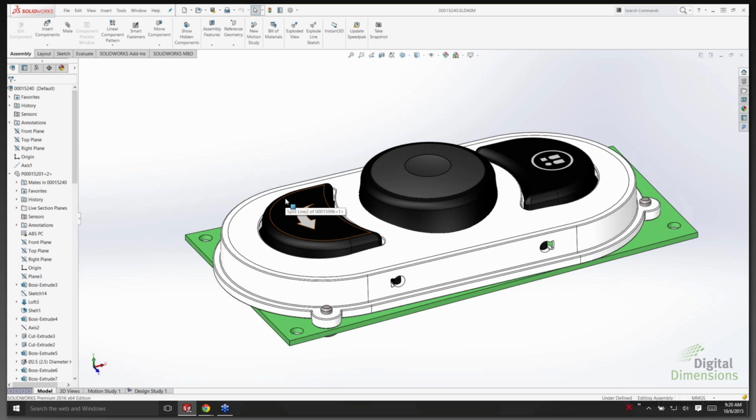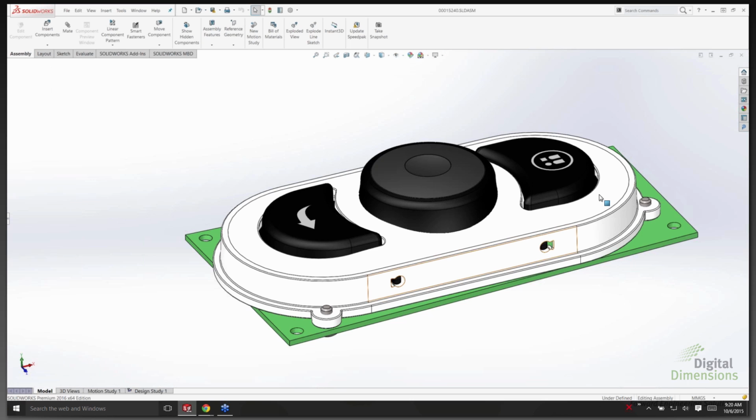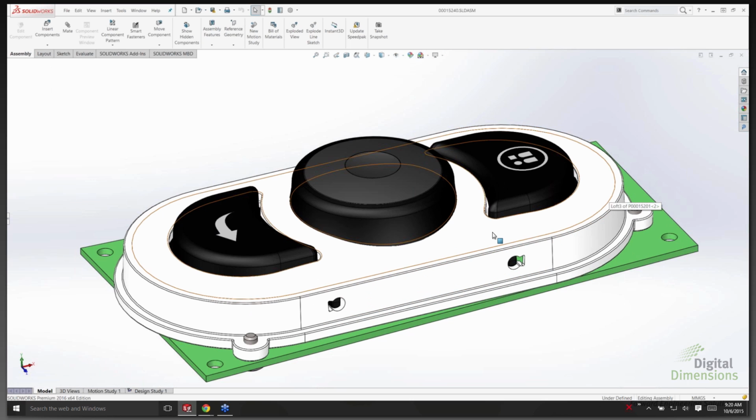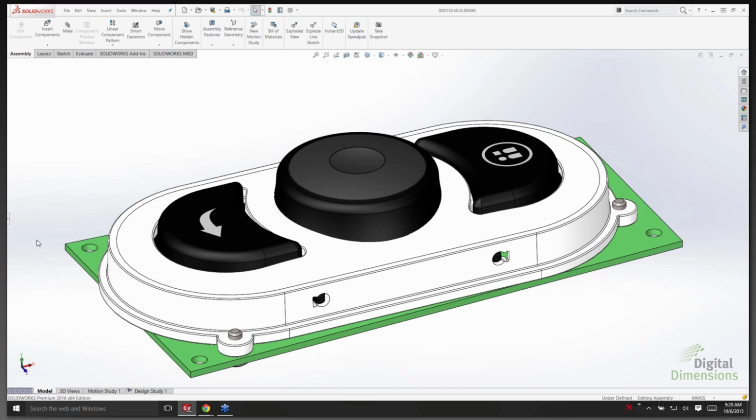All right. Now, the next enhancement I have here is probably one of the most groundbreaking that I've seen in quite a while from SOLIDWORKS. You'll notice that a lot of SOLIDWORKS users like to view their screen in this full screen scenario, right? They minimize the feature manager so that they can see what's going on with the model. The problem with this is when you try to go in and start editing different components or different features, you always had to open that thing back up. It would come back over your model or start shrinking your model so that you could select the features or select the sketches. This year in SOLIDWORKS 2016, we've introduced this new feature called a breadcrumb.